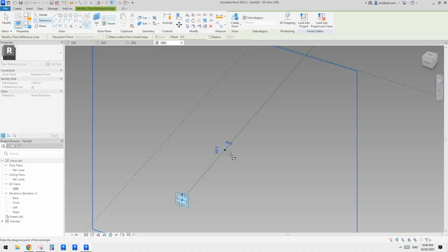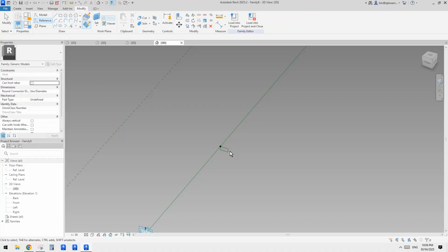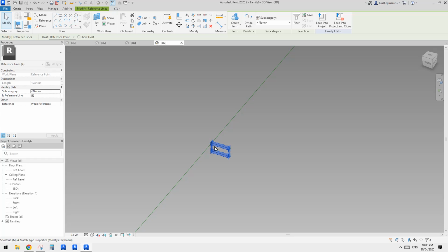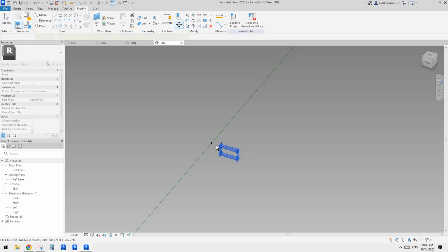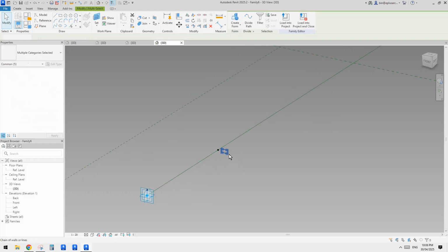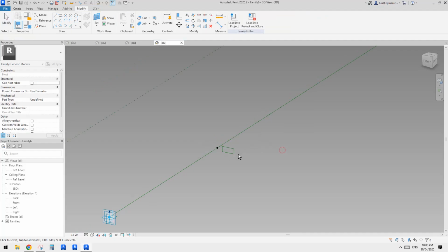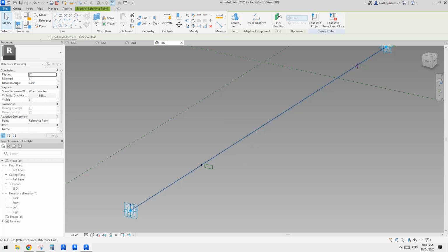I'll just roughly make it 100 by 200, for example. And also we need to offset it, so move it away, maybe 100. And also I want this one to be centered, so I just move it up by 50. So now you can see it's centered, offset, and then select it. Maybe make it slightly more than 200. 200 seems maybe 270, 240. Okay. And then copy this, Ctrl+C, select the point, pick new host, place it here.